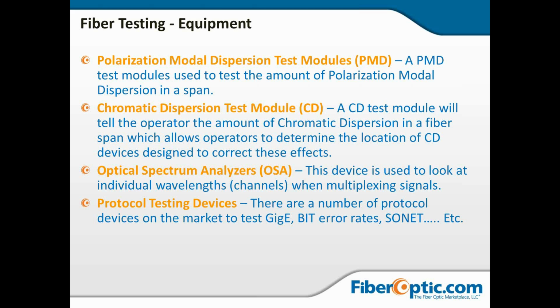I used to teach in class that there was no practical limit to the bandwidth on a single mode fiber. And with the rise and discovery of polarization mode dispersion and it coming to the forefront, we have realized that that's the limiting factor. PMD is going to cause us to either shorten our runs or limit our bandwidth over our existing distances, because it's just going to cause so much delay that the signal breaks up.